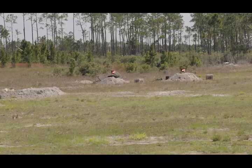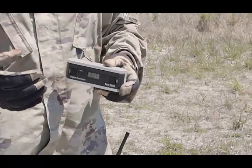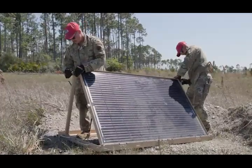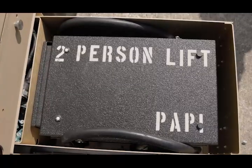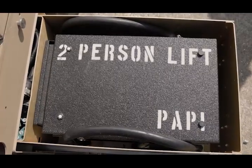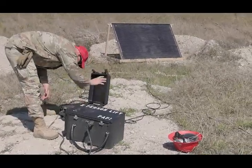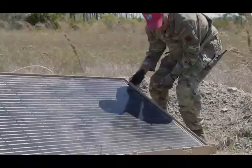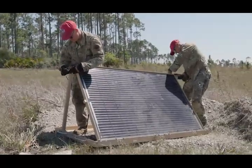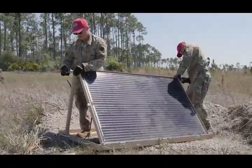The PAPI system includes 4 light head assemblies, 1 battery box, 1 digital inclinometer, 2 solar panels, and 20 ground stakes. The battery box is a rechargeable 50 amp-hour, 24-volt DC pack with an integrated controller. If AC power is lost, it automatically reverts to solar power. Each PAPI system has 2 300-watt portable solar panels, which can tilt from 0 to 70 degrees and should be pointed toward the equator for optimal charging.